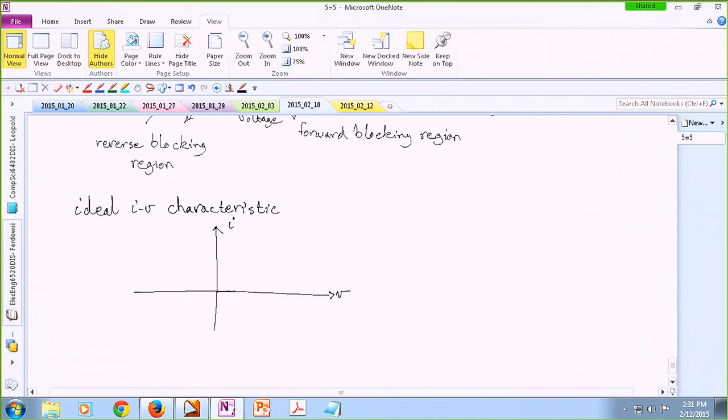The device can handle positive voltages. All right, when it is off, no problem, no current will pass through the device. It can handle positive currents when it is turned on. And it might be able to block a little bit of a negative voltage as well. All right, something like this. We don't really use the IGBT in that mode anyway. So as you can see, IGBTs are first quadrant switches.